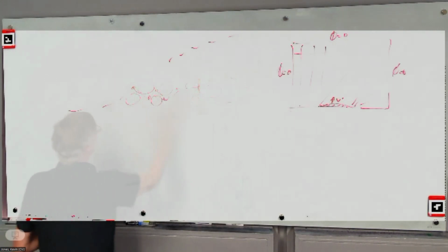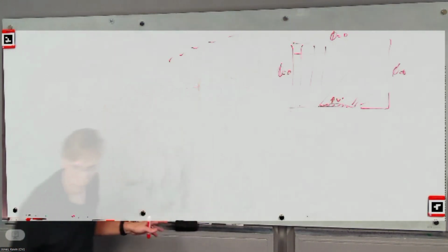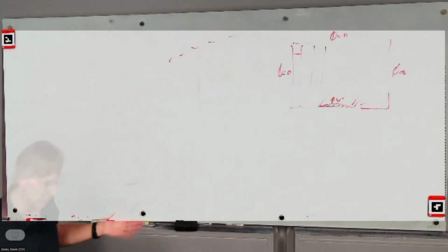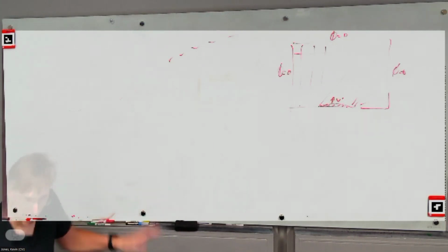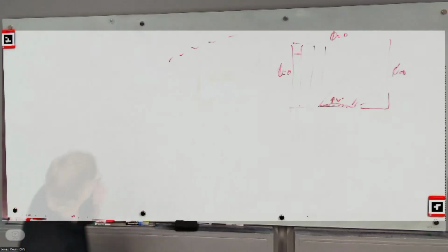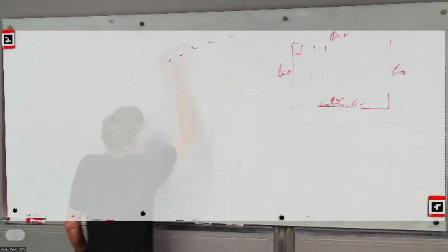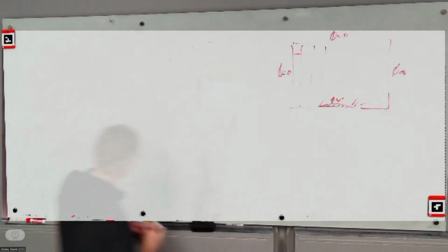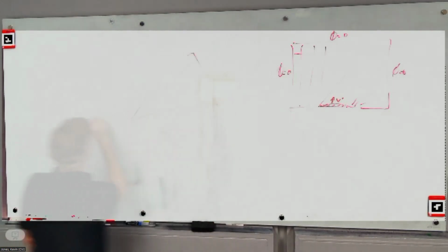So we were looking at finite wings that were unswept. In your vortex lattice method, I think pretty much everybody did some things where the wings were swept pretty far. And one thing that the vortex lattice method misses is that if you sweep the wing far enough, like a delta wing here, with flow coming in, you're getting this bound circulation stuck on the airfoil here.